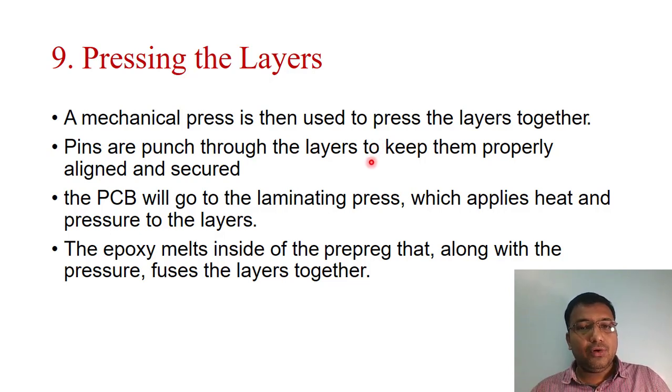Then the PCB will go to the lamination process, which applies heat and pressure to the layers. The epoxy melts through, and the prepreg along with the pressure fuses the layers together.